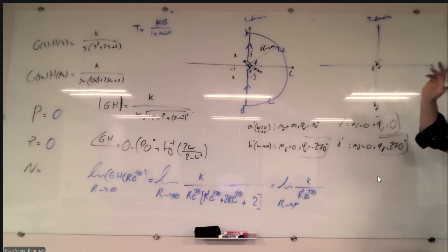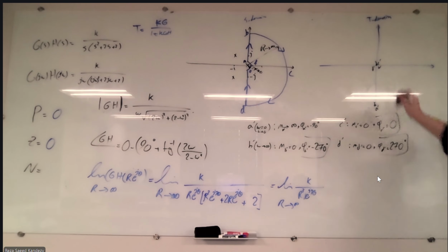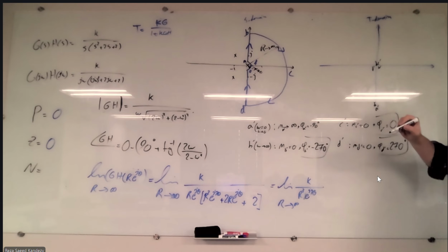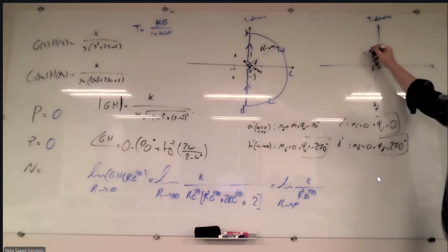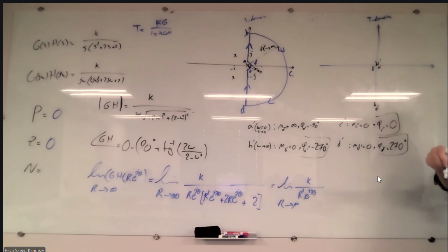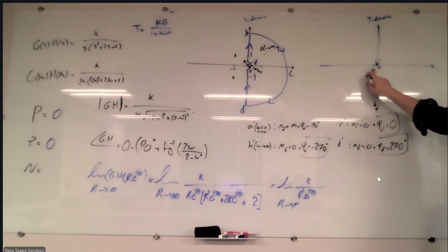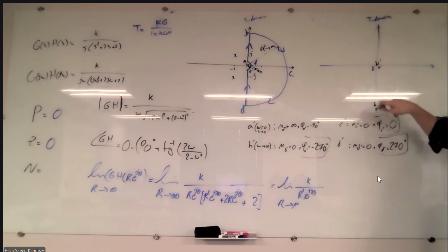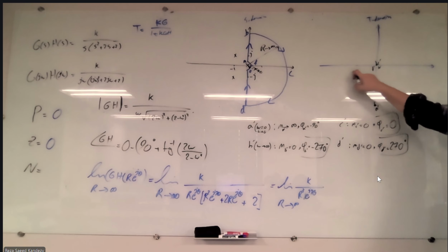Now, there is another point. We don't know how they would reach out. We know that this is going to be going up and then down, but at what point would it go down? We need to find when this trajectory would cross the real axis, which is omega equal to 0.